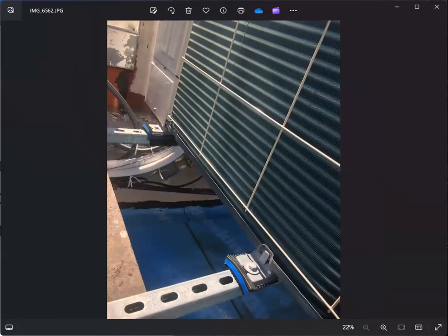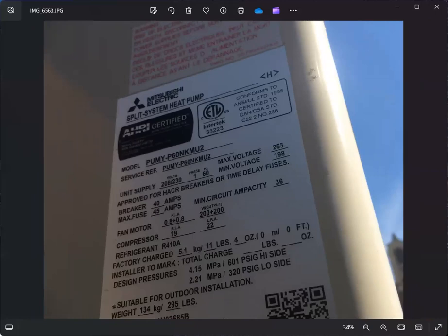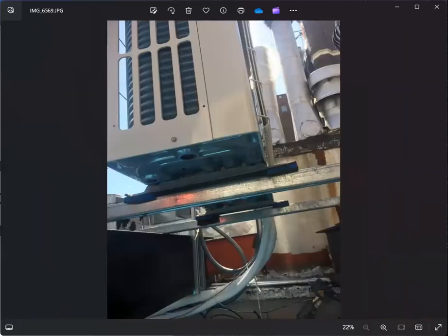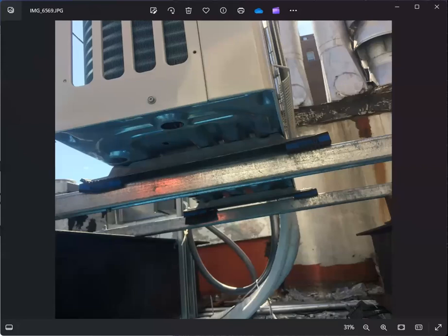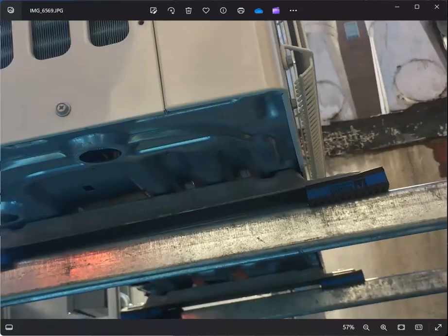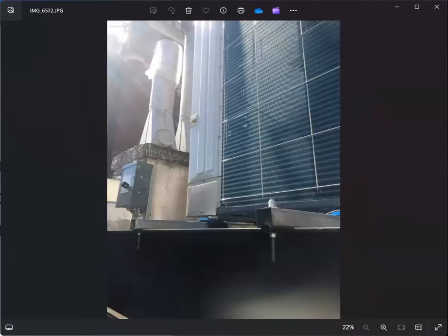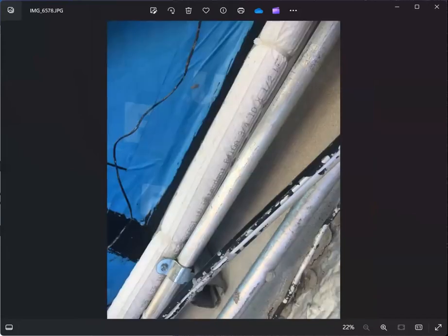You're going to check the drawing if that is the right or proper way to install, or the specified vibration isolator. This is the heat pump or the condenser unit model number. And that's the photo that I took of the four corners of the support, the mounting support with vibration rubber, complete with the anchor bolt. Same thing.